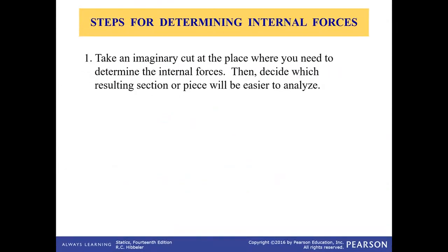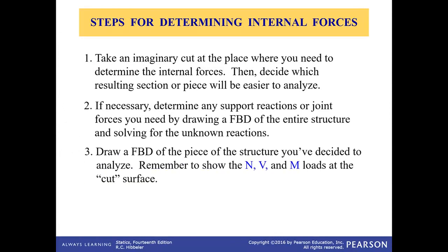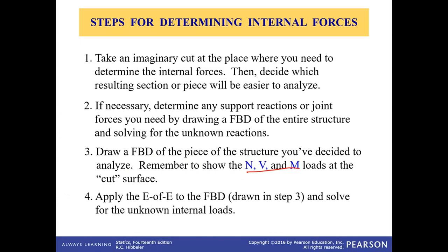Steps for problem solving: take an imaginary cut at the place where you need to determine the internal forces, and then decide which side of the section will be easier to analyze. If required, calculate the support reactions. Name the internal forces N, V, and M, so normal, shear, and bending moment, and apply equations of equilibrium and solve for the unknown internal loads.